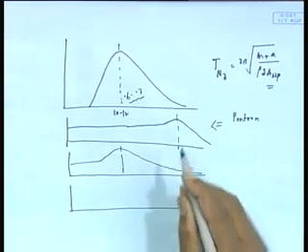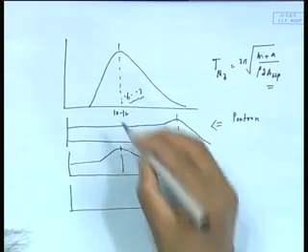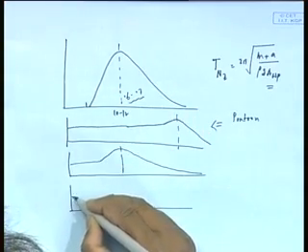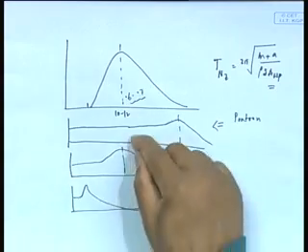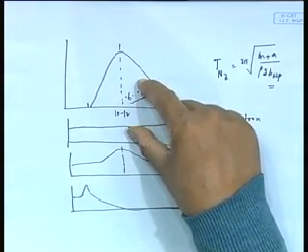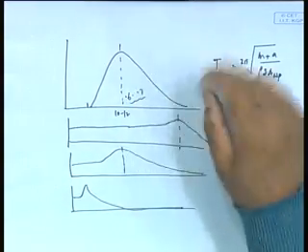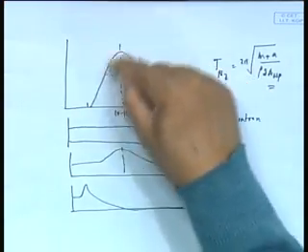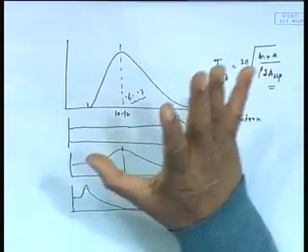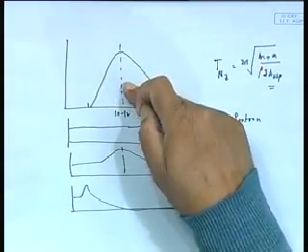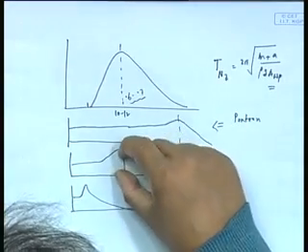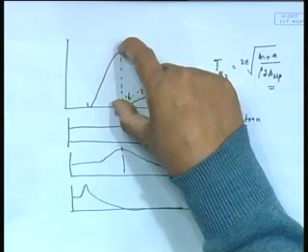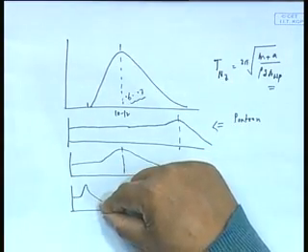Take an offshore structure, you design an offshore structure to make sure that its peak is here. So, it is something like that. Now, multiply this with this, what will you get? Fairly large response, but not that bad, more or less same as this. You will get response 1 type in this particular wave. This you are going to get much worse, because here this high and this high is more or less close by. This you are going to get practically no response.